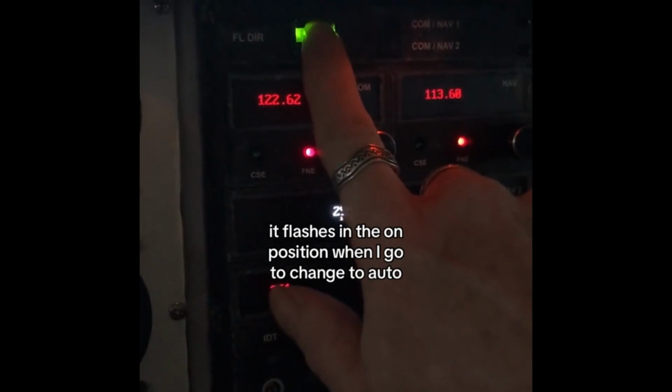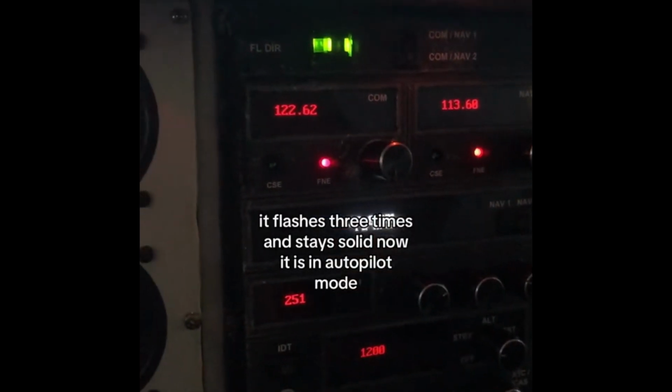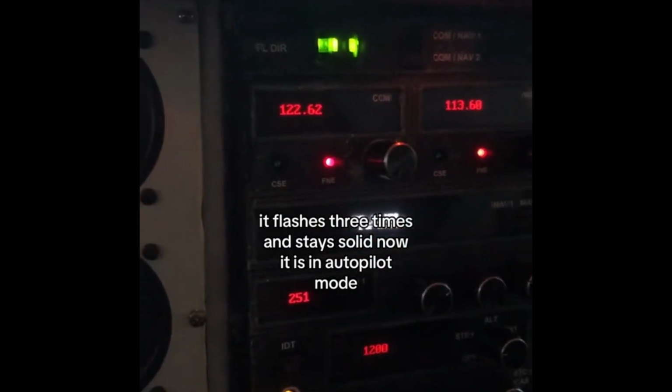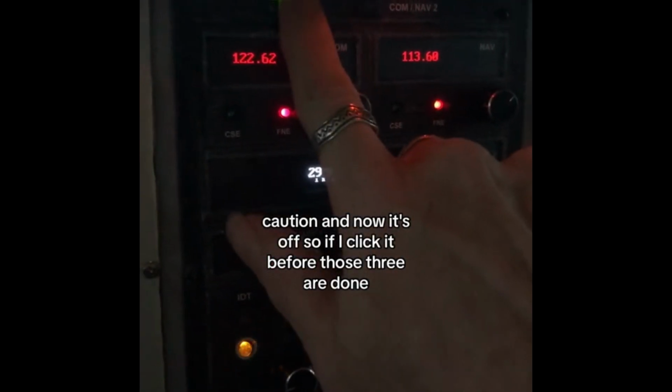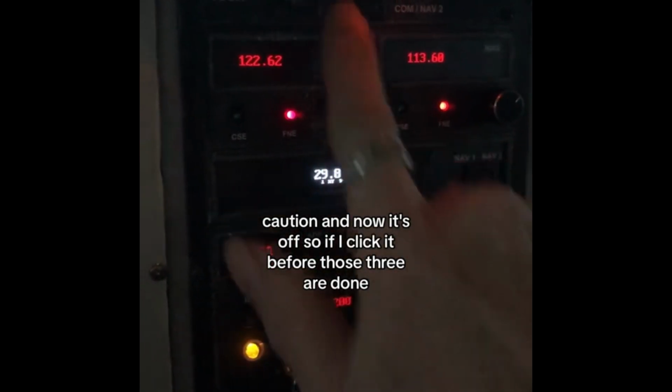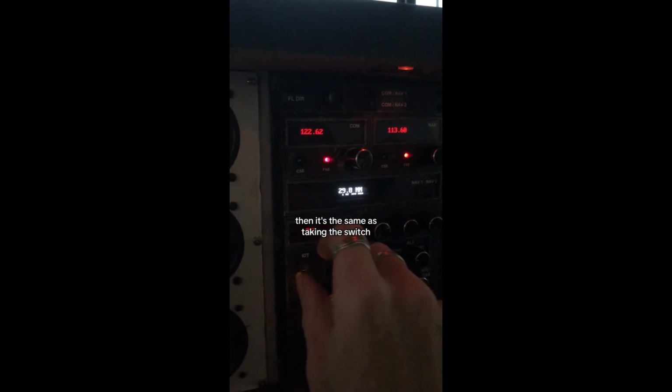When I go to change to auto, it flashes 3 times and it stays solid. Now it is in autopilot mode. Caution. And now it's off. So if I click it before those 3 are done, then it's the same as taking the switch, putting it to auto, and then putting it back to off.